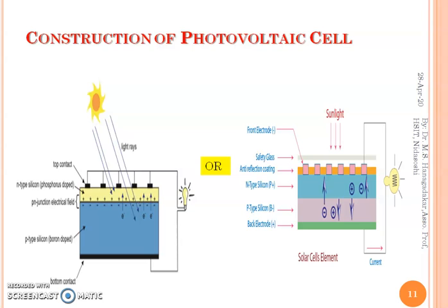This is placed over the P type silicon, which is doped with boron and has a thickness of 250 to 300 micrometers. The N type silicon slice is placed over the P type silicon, and both are sandwiched at the interface. There is the formation of a p-n junction diode.